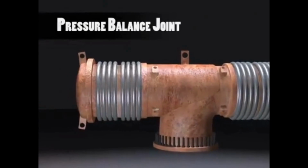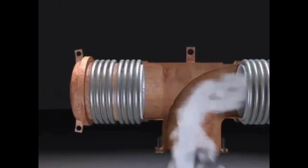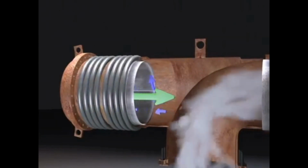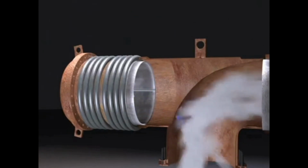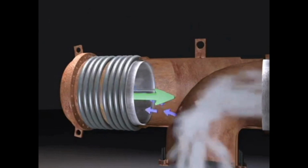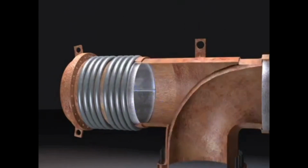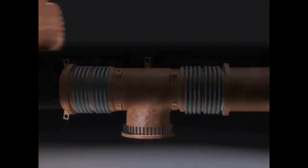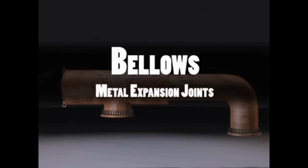The balance joint is an extended piece of pipe on the end that directs the expansion of the main pipe. Holes in the main pipe allow the pressure from steam to fill the balance joint. This pressure counteracts the internal pressure, forcing the pipe to expand towards the bellows. Together, this allows for a more efficient system for generating electricity.